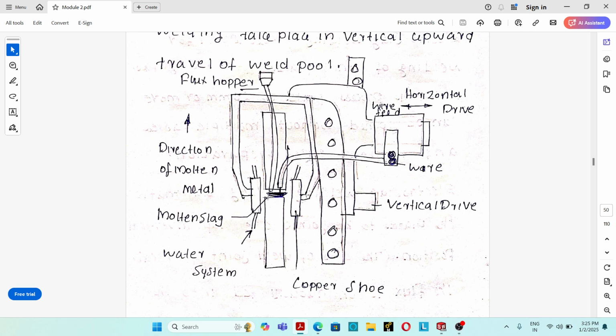Due to the temperature of the electric arc, the flux melts and molten slag is produced. Once the molten slag is produced, the arc extinguishes and the electric current passes through the conductive molten slag. Heat is produced due to the resistance offered by the conductive molten slag to the flow of electric current.